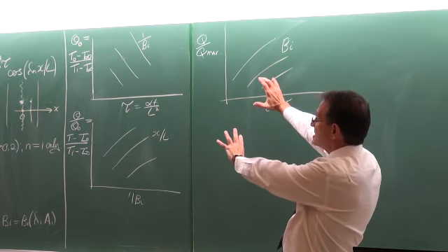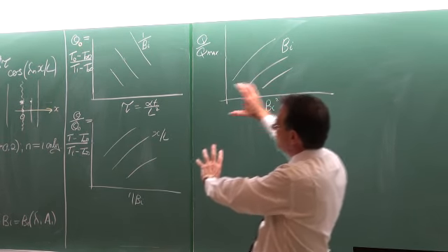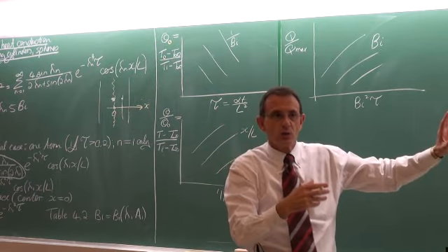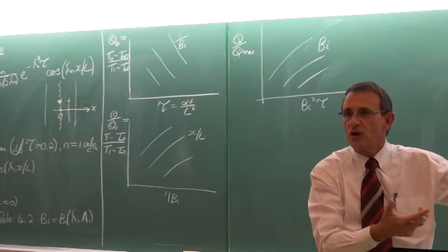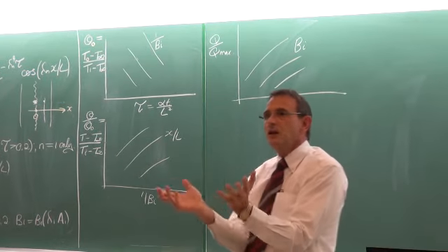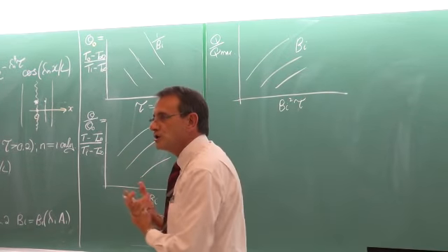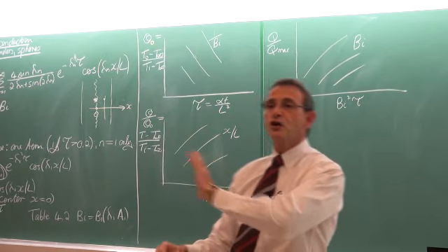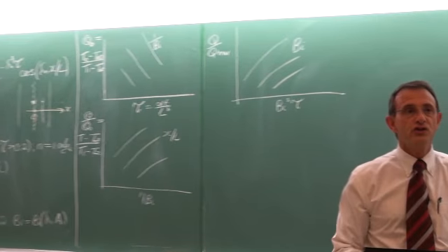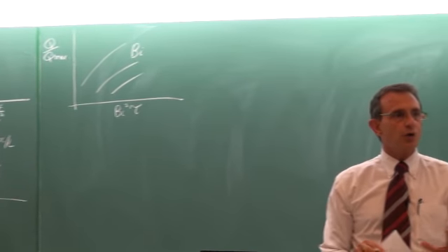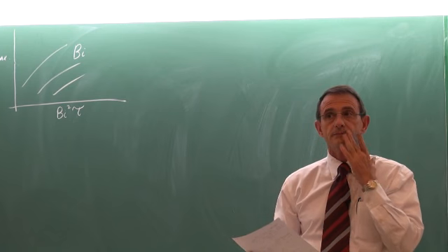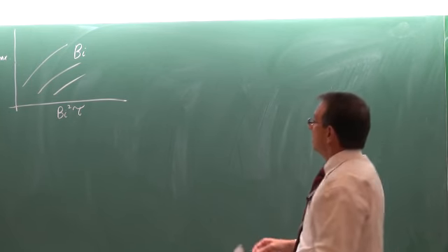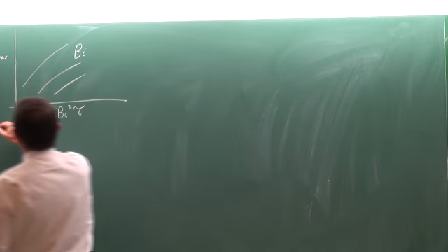Okay. Now one of these sets of graphs would be valid for the plane wall. On the next page, there's one for the cylinders, and the third one is for the spheres. So depending on the geometry, you're going to use the correct Heisler chart. Okay, so that is the theory part of paragraph 4.3. Before we go on to a problem, any questions on the theory? Nothing, okay.